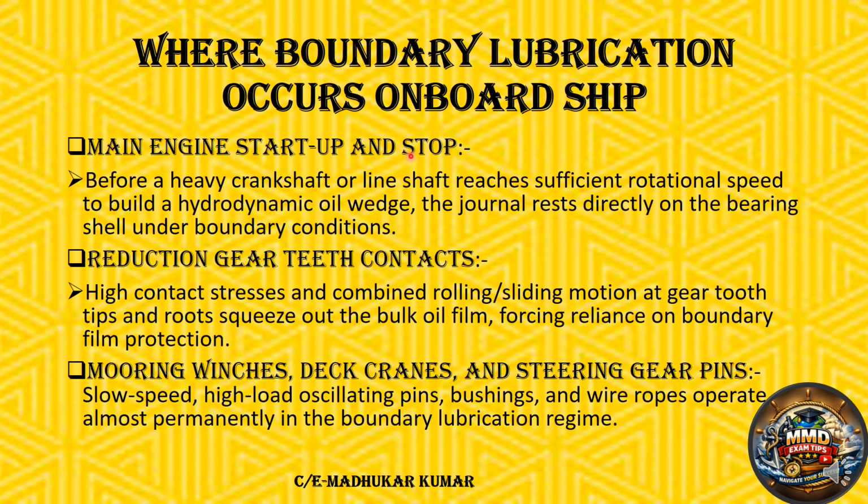At start up and stop, before the heavy crankshaft or the line shaft reaches sufficient rotational speed, we have seen in the diagram boundary lubrication, then mixed lubrication, and then hydrodynamic lubrication starts. Once the hydrodynamic wedge is formed, hydrodynamic lubrication will be there. It's a transitional phase.